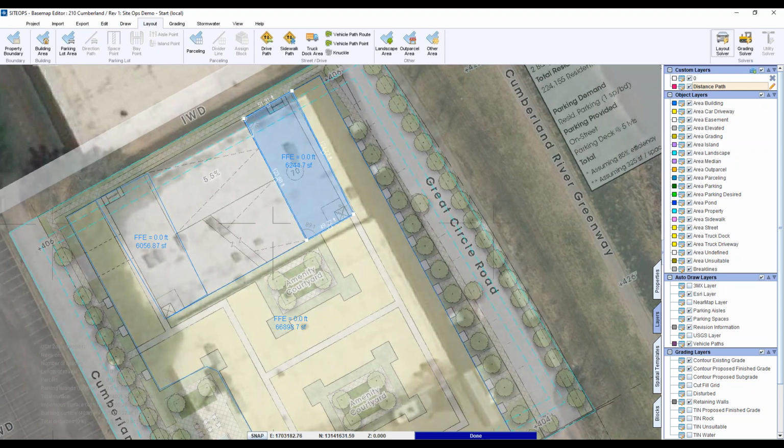So what I do in here is, when I get these sloped areas here, I'll end up moving that line over. What I'll end up doing is pinning, do a link to that side and that side, and a link to that side and that side, and delink these sides, and then let it go 6% slope. And then I'm setting this to be 5.5 feet over this level.